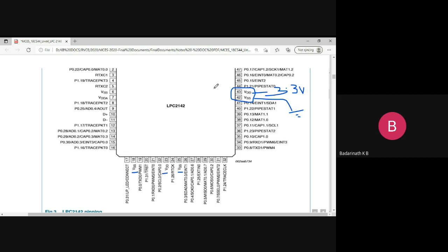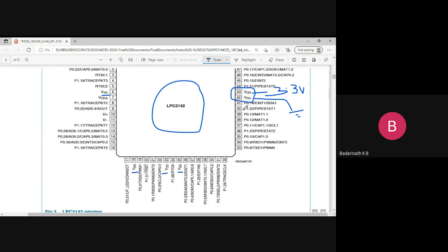Because of the circuits present inside. Yes or no? The blocks which are near to that can take from here, and the blocks which are here can take from that. So proper power distribution happens, and there is no overloading of a particular pin or particular line. They can distribute properly. See here also one substrate, one VSS ground is there. So now we have seen that there are a few pins available on this chip which provide power supply and ground. Multiple pins are provided for proper power distribution. So what are the names of the power supply pins? VDD and VSS.